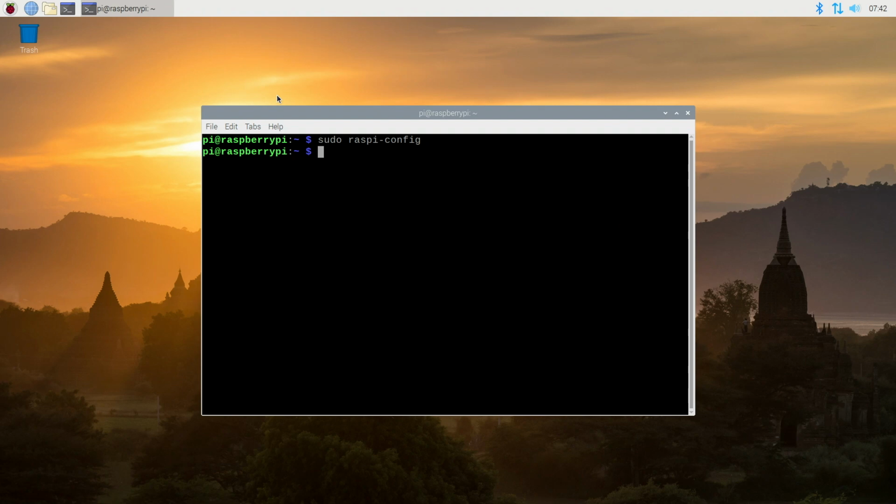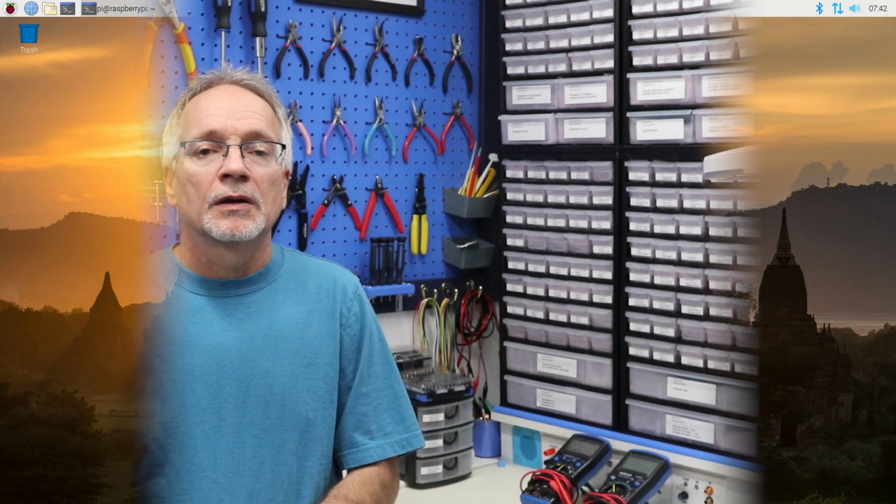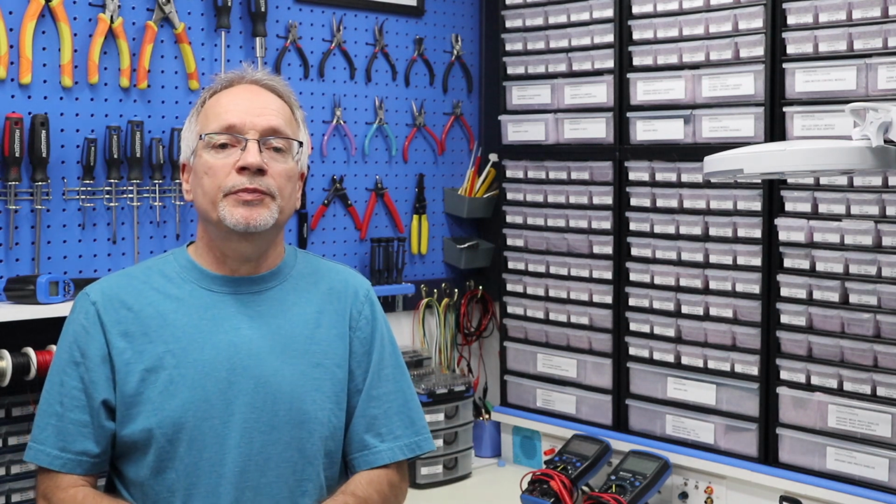Now, in order to test to see that the port is enabled, there's a simple way of doing that. You can use an ls command, which is the command that Linux uses in order to list directory contents. So if you do ls, space, /dev/, star, I2C, star, and hit enter, you should get this result with I2C-1, and that indicates that the I2C-1 port is now available. And if you've done this, you have now successfully set up your Raspberry Pi for our I2C experiments. So now that we have our Raspberry Pi set up, we're ready to begin our experiments.